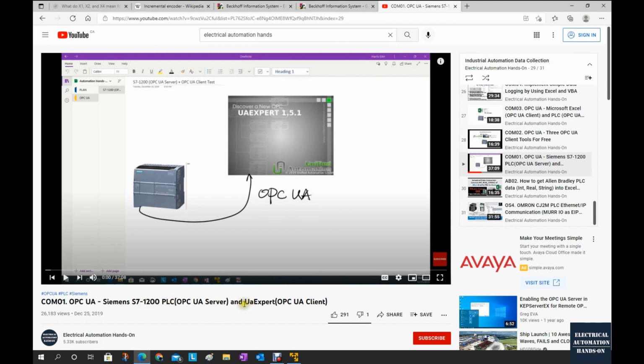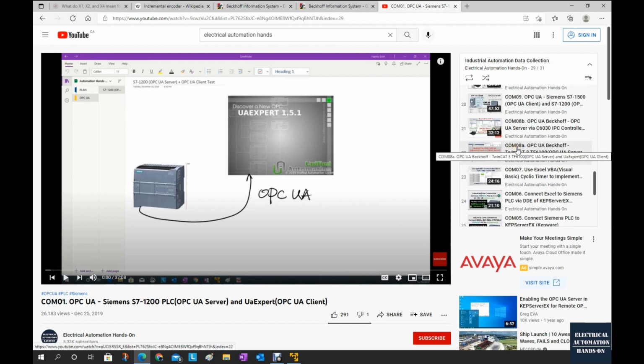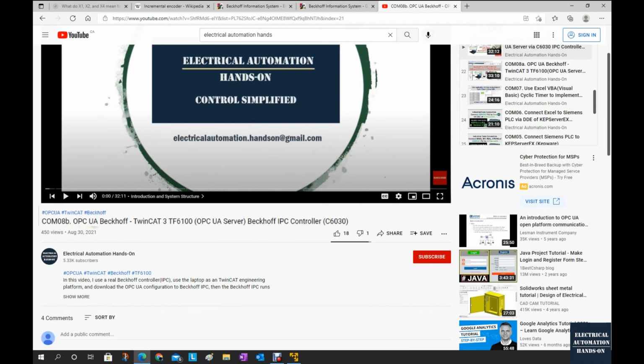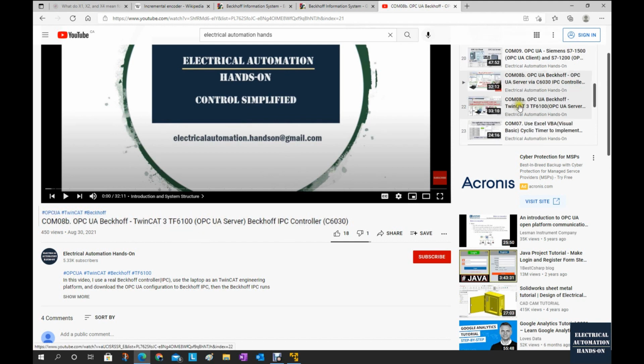Especially in this test, the S7-1200 PLC will run as the OPC UA server. And also, if you want to check how we can implement the OPC UA server function in the Beckhoff system, you can find another two videos in this playlist. If you go up, find COM08A and 08B, especially COM08B. This is the most recent video I published. In this video, I showed how we can implement the OPC UA server using one actual Beckhoff controller, the C6030, running as an OPC UA server function. These three videos show how we can implement the OPC UA server function.